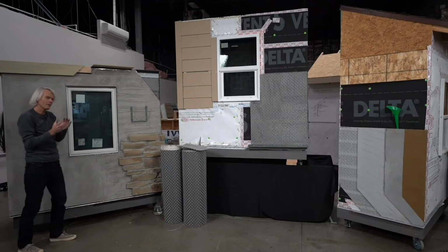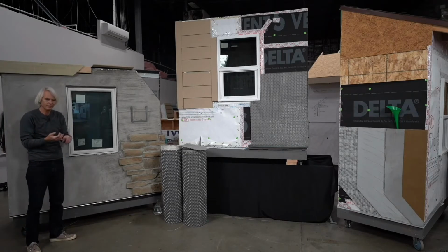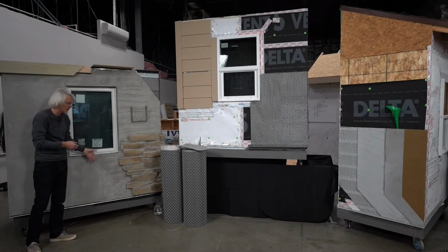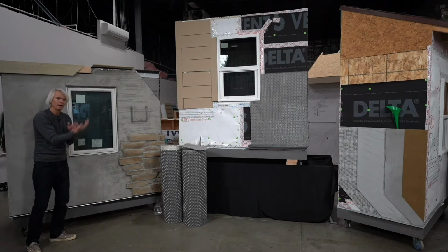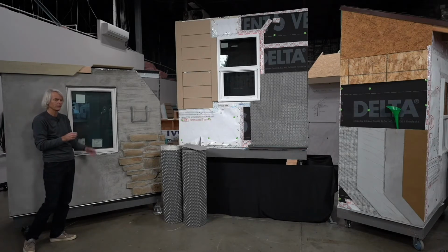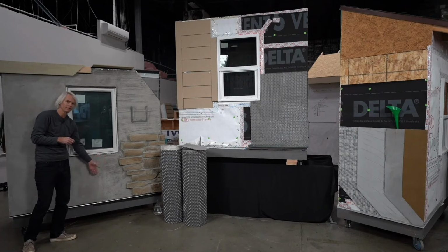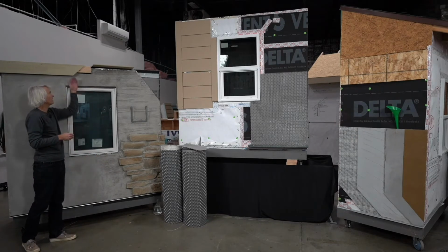Now, when we talk about a rain screen, there's a vented rain screen, I should say first, and a ventilated rain screen. A vented rain screen is one where we've just opened the bottom area of that wall up to allow air or water to pass in or out of that. The air is, of course, for drying. So when we talk about a ventilated rain screen, we're typically going to have ventilation at the bottom of the wall, but also at the top of the wall.